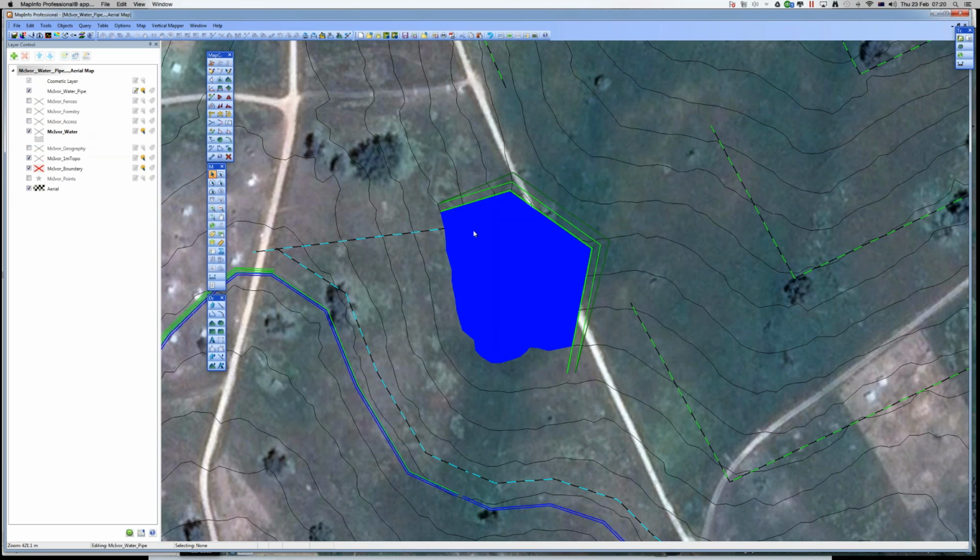So whatever you select on the map will automatically be bold over in here. I haven't got other layers on, but say I put access on now, I click the access layer, it becomes bold over here. So that can help you when you're seeing whether you've put something on the wrong layer, for example, which if you have, you can activate that layer,